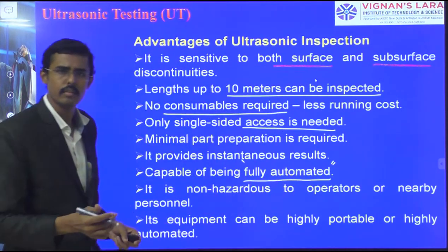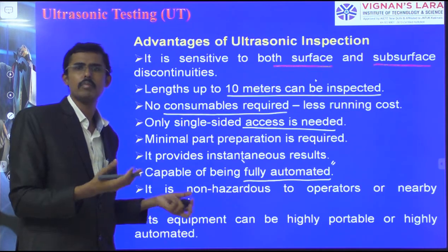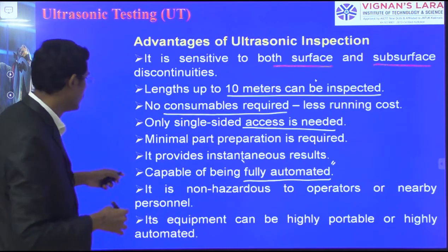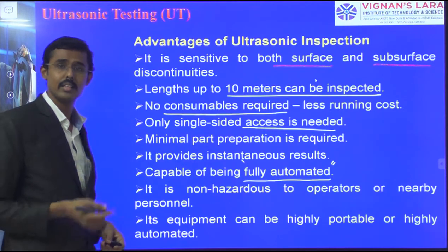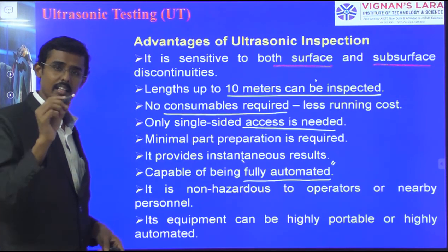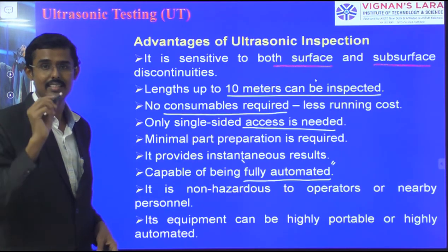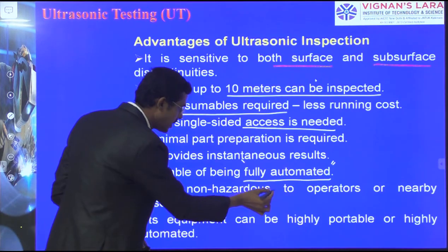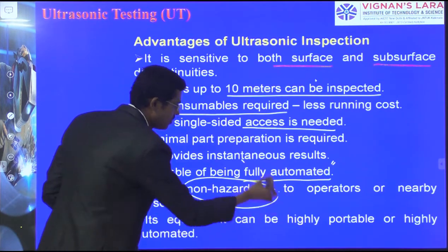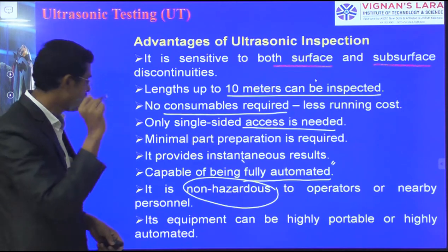This is fully automated. The operator operates, and even the machine setup we are able to do. It is non-hazardous to the operators. In radiography, the radiations which come out, X-rays or gamma rays, are harmful. But here it is non-harmful. Ultrasonic waves are passed there.